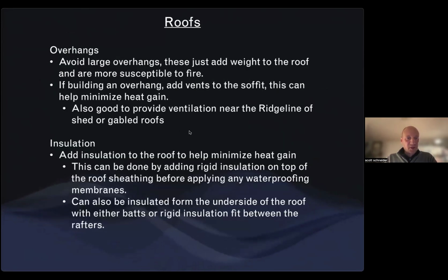Overhangs, I would avoid large overhangs, but overhangs are actually a great place to put a vent for a roof. You can have ridge vents at the very top of the roof, and then a soffit vent at the bottom of the roof, and that helps airflow.